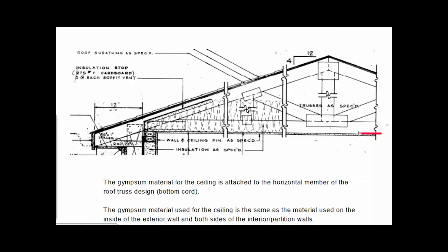The Finish Ceiling 1 is indicated by the bottom of the roof framing. The ceiling object will be attached to the bottom of the roof framing. This is why the ceiling object will be placed on the Finished Ceiling 1 level.